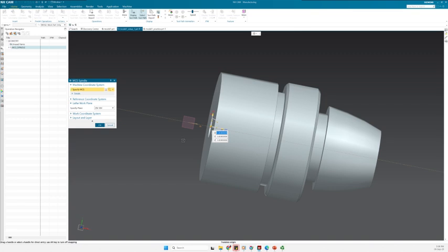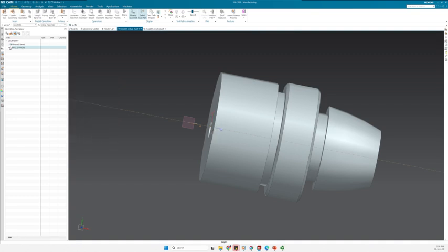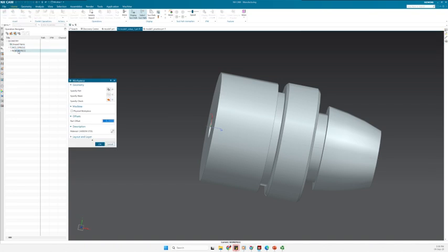And if you change it and you see that there is still a problem, especially for your assignment, it means that you need to go back and perhaps remodel your part so that it would be in the same axis. So here, this is the ZX of the machine itself. So this is fine for me and I don't need to do anything, and I just click OK. Next, I will click on the plus sign beside this machine coordinate system spindle. And now I have the workpiece. So here I double click again, and now I can define the workpiece.